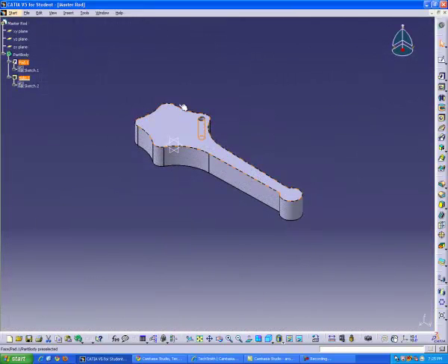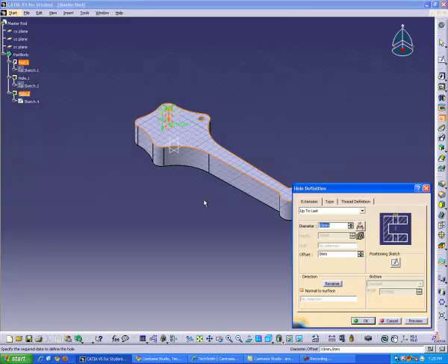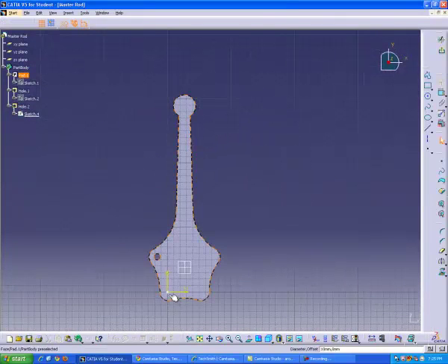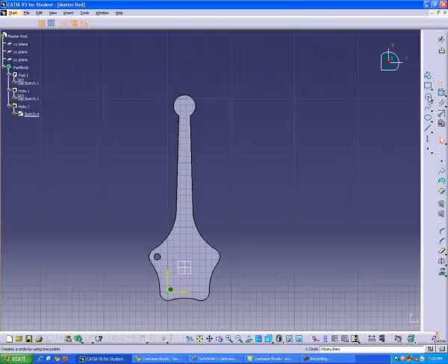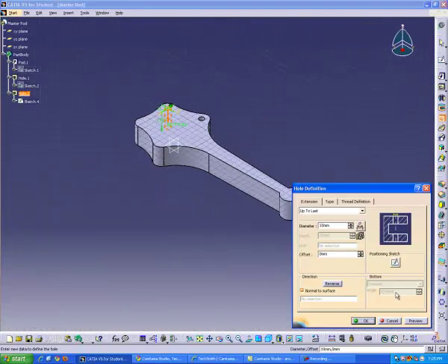The hole should be up to last and 10 millimeters. Repeat this for the next 3 holes, all around the outside. Concentric, up to last, 10 millimeters.